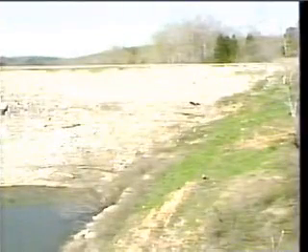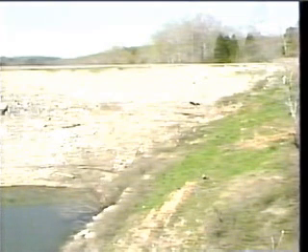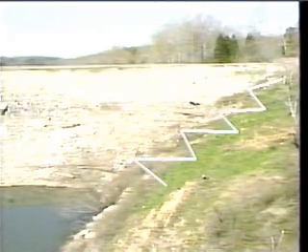You should carefully inspect the areas where the abutment contacts the embankment. These areas are called the groins. The groins are susceptible to seepage problems and runoff erosion. You inspect the groins by walking along this contact surface before you leave the slope.